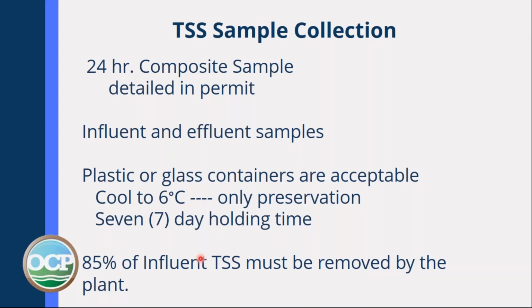It doesn't matter for TSS whether you save in plastic or glass, but the sample must be cooled to 6 degrees centigrade, and you have 7 days to get that sample tested. Of course, you're not going to wait until day 7 to get it tested. You're going to get it tested before that, but you have up to 7 days.